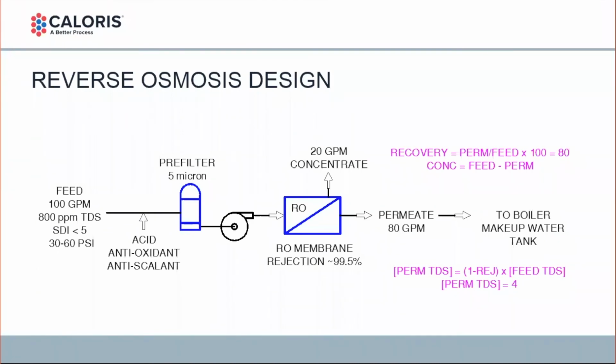Okay, so this next slide is going to cover what goes into the design of an RO. Process engineers will typically use modeling software to determine maximum recovery and permeate flows based on the feed water mineral analysis. So for an RO, the main equipment, for pre-treatment, you're going to have to have your chemical pumps.